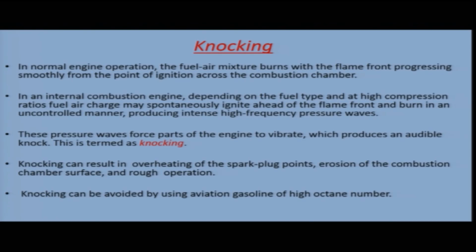It can result in overheating of the spark plug points. The combustion chamber surfaces may be eroded, and the engine may operate roughly. So, knocking has many disadvantages: overheating of the spark plug points, erosion of the combustion chamber surface, and rough operation. Knocking can be avoided by using aviation gasoline of high octane number. High octane number fuel is desirable as it has anti-knocking qualities.